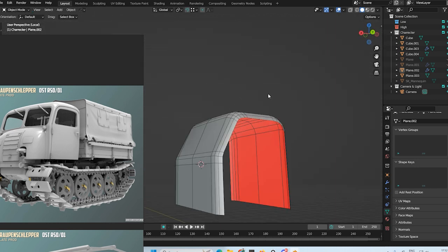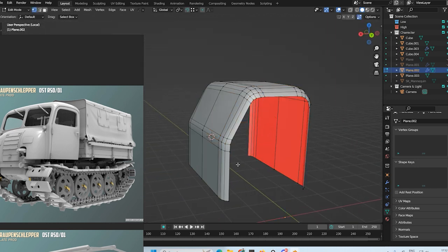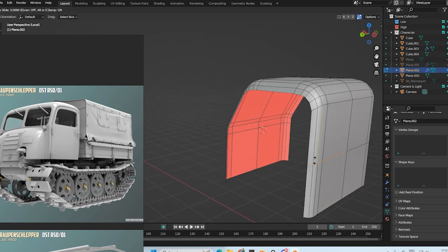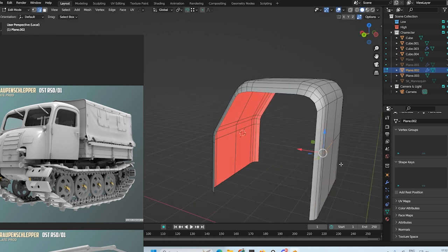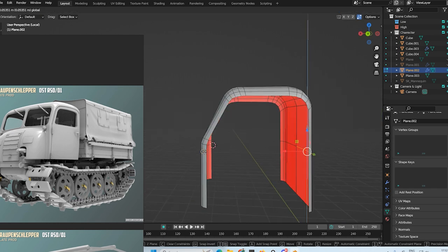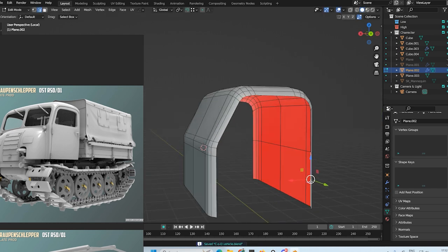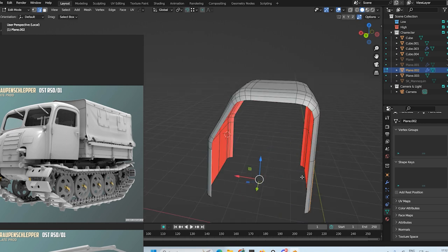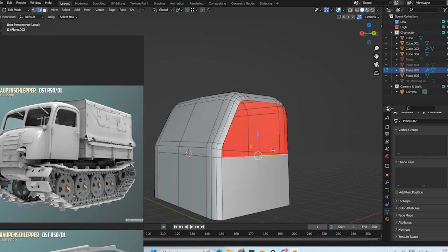Now we can make a door out of it. S Z 0, align to the vertices, click edges and F to join the areas.